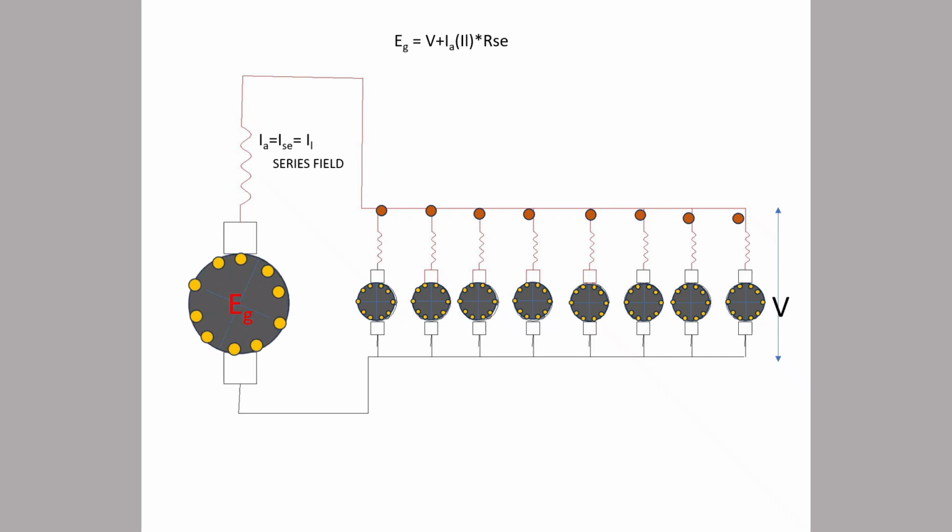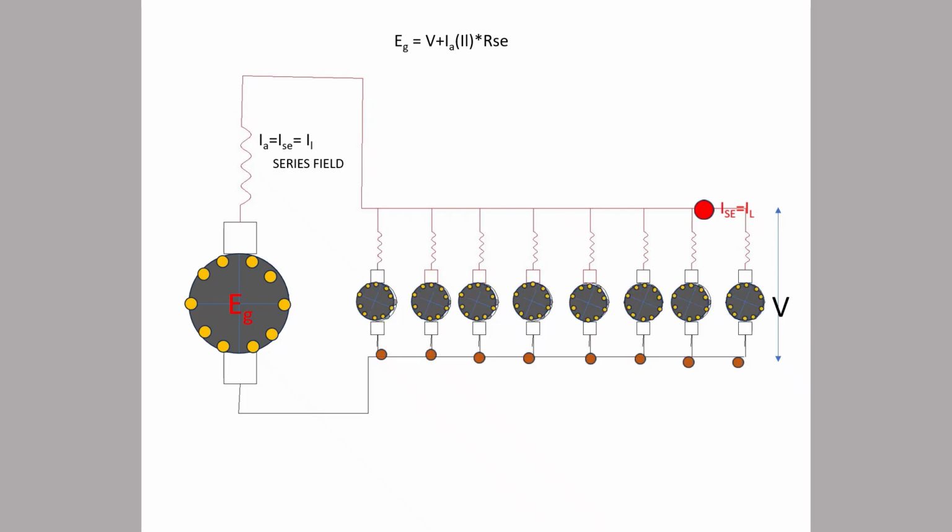So in our old electric locomotives, we were using the DC series motor. Why the DC series motor? Because it has good starting torque. When the train is stationary, to start it needs power, more starting torque. So from stall to start, it is better to use the DC series motor in an electric locomotive. It will be helpful.